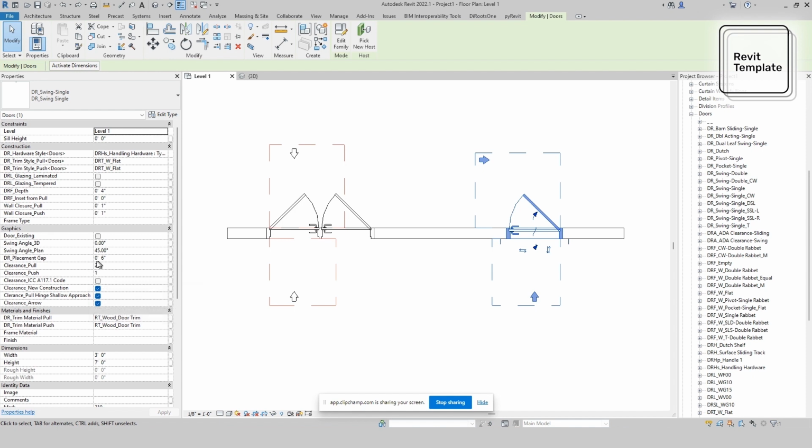These are integer parameters, and each one is set per side. To adjust the parameters, simply set from between 0 and 3. 0 will turn off the parameter, 1 indicates a forward approach, 2 indicates a latch approach, and 3 indicates a hinge approach. If a user sets anything outside of these parameters, there is no approach that will show up.